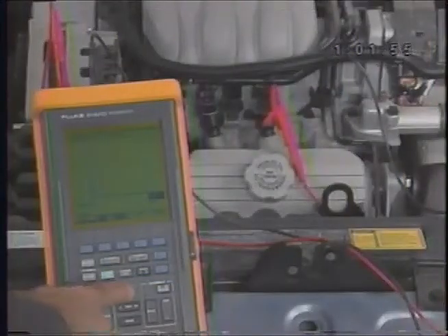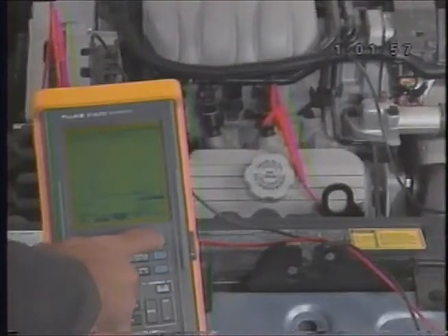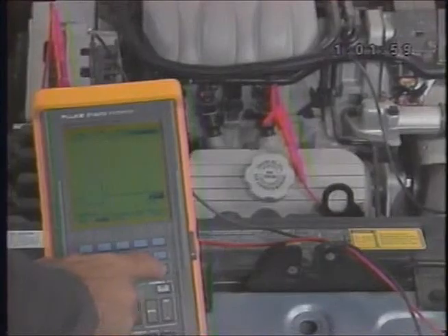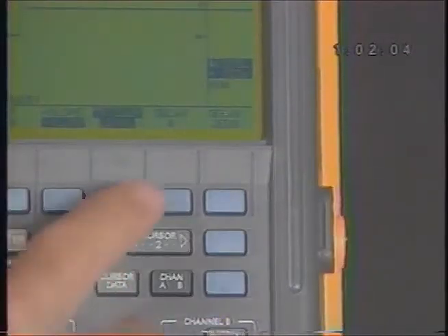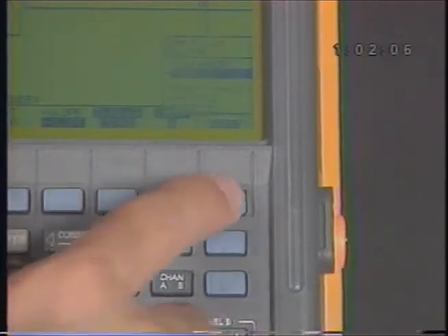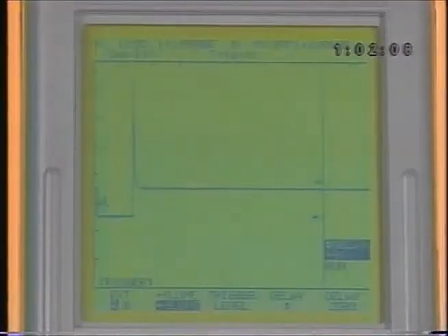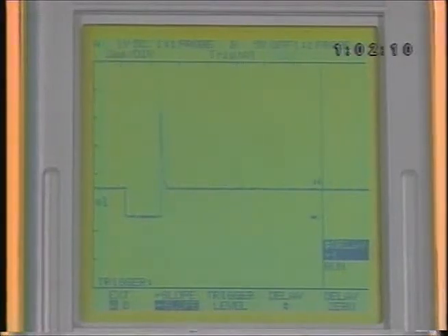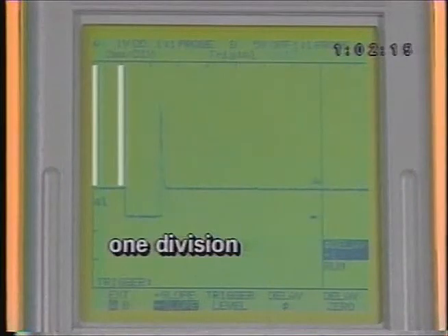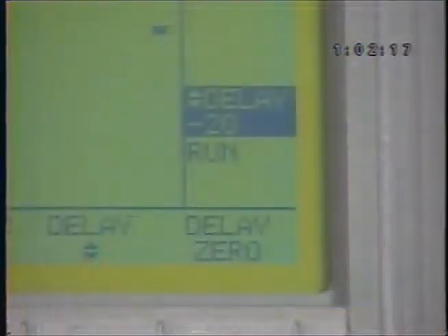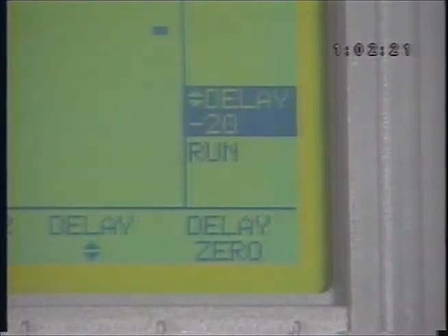You'll learn about trigger delay, a feature that allows you to tell Scopemeter to begin drawing the trace before or after the voltage crosses the trigger level. For example, setting the trigger delay to -1 tells Scopemeter to begin drawing the trace one time division before voltage crosses the trigger. That moves the waveform one division to the right, which makes viewing some signals easier. This is a unique feature of a digital oscilloscope. Scopemeter allows you to set the trigger delay from -20 divisions to +640 divisions.